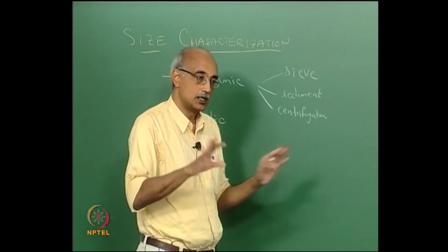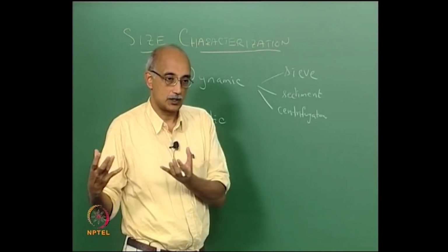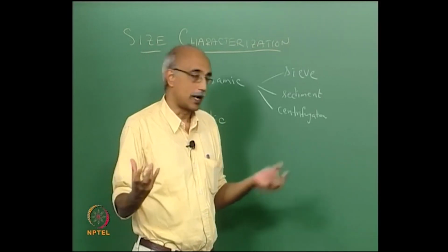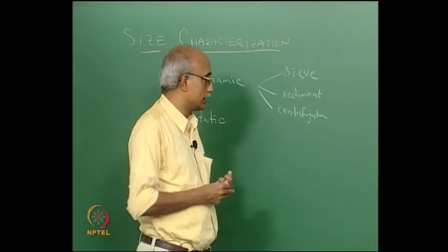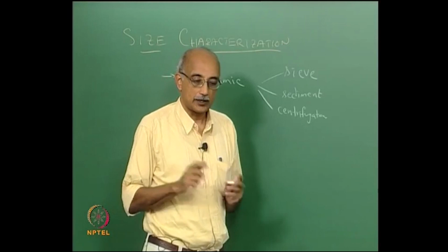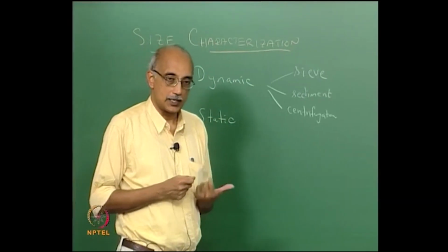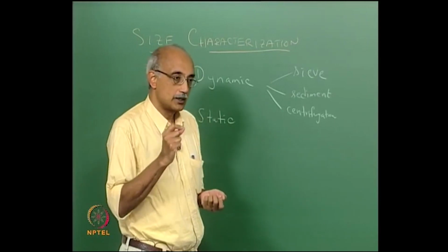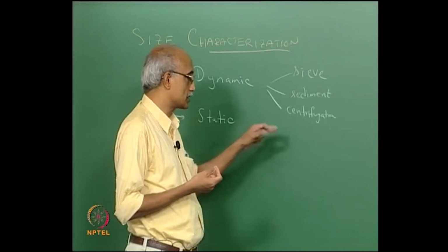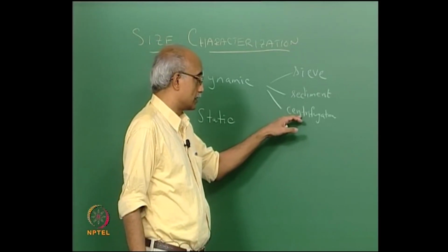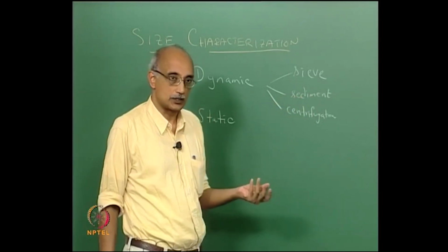So, you achieve separation by size, and then you can capture the samples and do sieve analysis to characterize their size. Now, in this case, the characteristic of a particle that you are using to do your dynamic size analysis is its action under a centrifugal field, which is a supplement to the gravitational field that you experience in sedimentation.